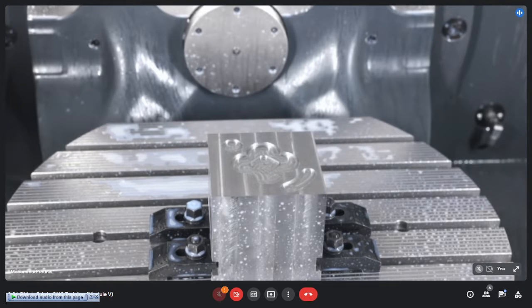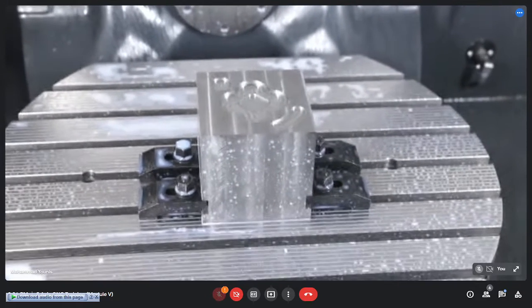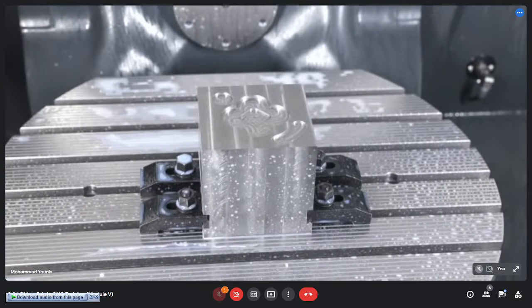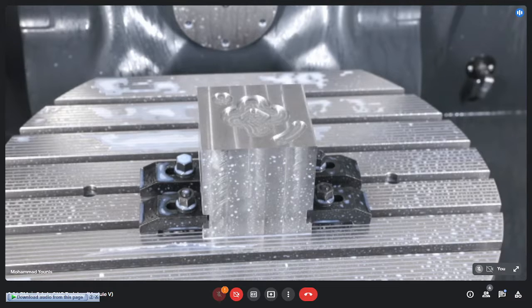So here, before doing that, you can see how complex the shapes can be that we can machine. So this was all about 3 axis pocket milling. Now I'll directly run the 5 axis program. But before doing that, I'll be removing the material. I'll be doing a facing operation so that we can start our new cycle.